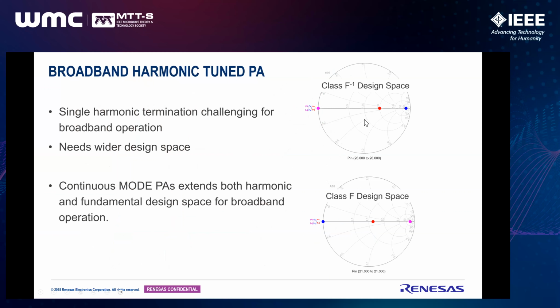So in class B, current already reaches the Imax of the device. So this is normalized 1. That is the Imax of the device. If you start introducing reactive components there, it will start peaking left and right, which is going to cross the device Imax. Although mathematically you will find a solution, it's not going to be a realistic solution, and the efficiency and all the solutions will be misleading from the practical ones.